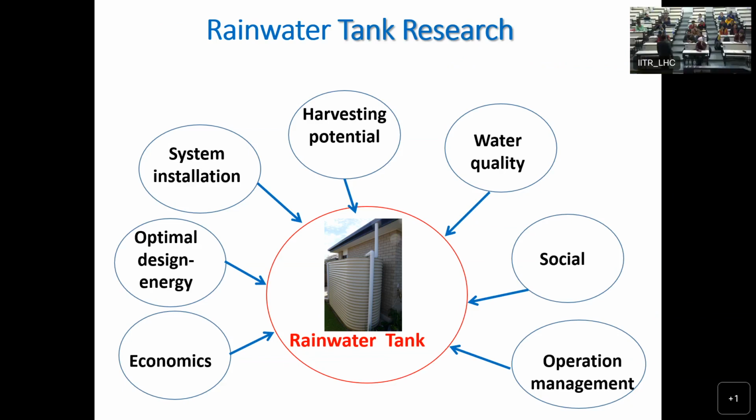So then why do we need, that means we are allowing water to hit the ground and then we are collecting it. If you are making a combined tank, through the pipe, filters, and then the pipe directly moves that rainwater to the storage tank, which is connected to the stormwater delivery. Is it possible? Then you are increasing the volume, but you are deteriorating the water quality. So maybe then some rainwater treatment is needed, since the combined volume is increasing.